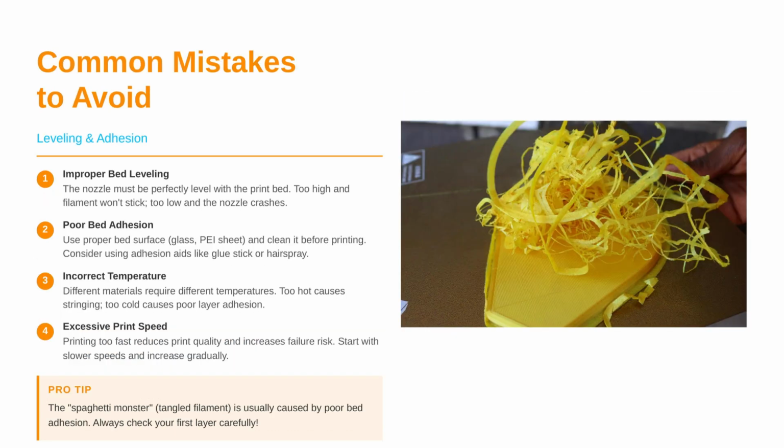Common mistakes to avoid. We have established the additive manufacturing process, but the transition from theory to successful execution often encounters specific technical hurdles. The most frequent cause of print failure stems from inadequate first-layer adhesion, a critical interface that determines the structural integrity of the entire object. This issue is fundamentally rooted in two parameters: improper bed leveling and poor surface preparation. Bed leveling ensures the nozzle maintains a consistent, micrometer-precise distance from the build plate across the entire plane.